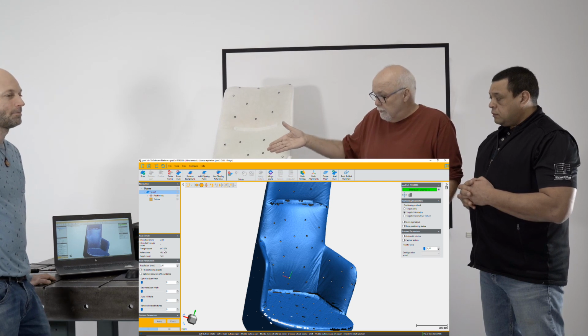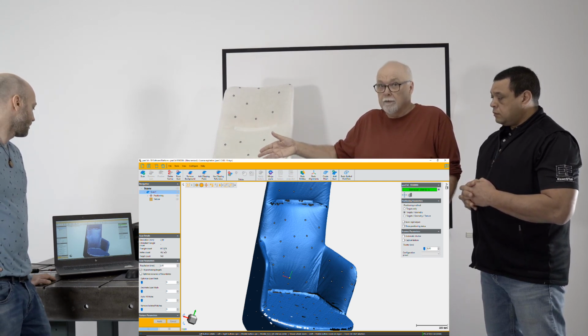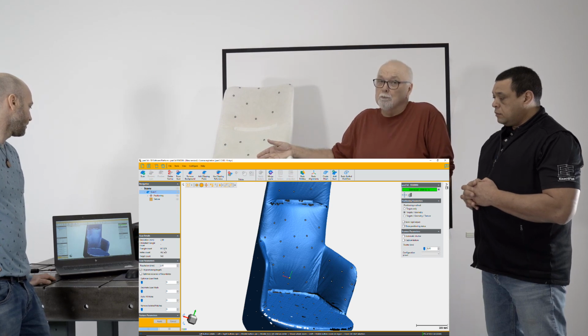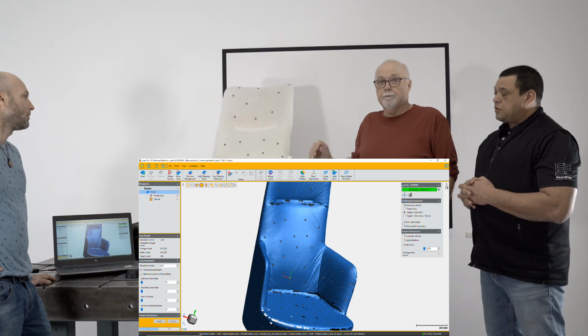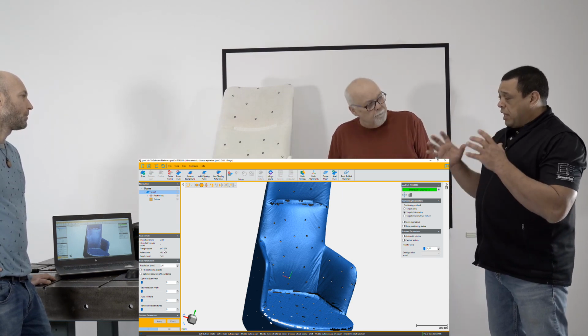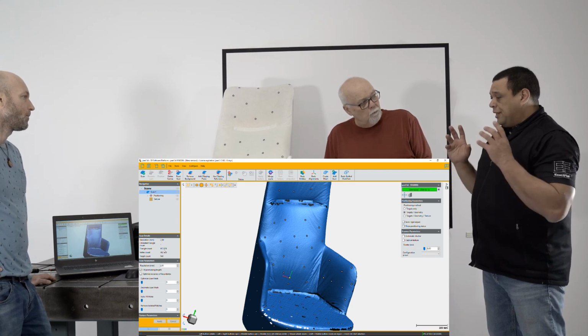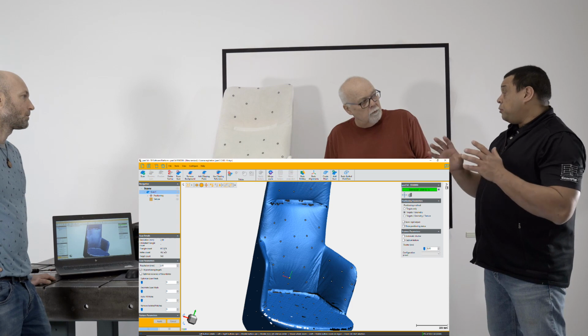But what I'm showing here is that you do not need to scan at 1mm. 2mm is plenty. You could probably scan at 4 on something like this and still be fine. That's just a matter of finding out what works for you. Because this is a balance of resolution and accurate results, but also time. You don't want to take too much time to do this, right?